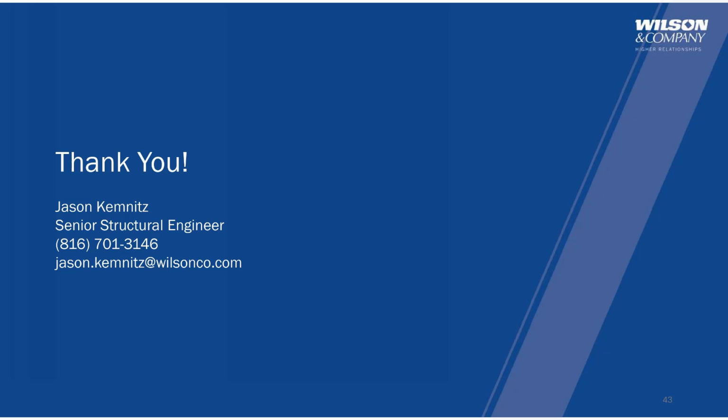Box culvert would take about a solid month. And then if you go next to SDCL, you're looking at maybe 2 months. The traditional, you're looking at maybe 3 months, minimum, right? So I think it's the cost savings on the ground for everybody all around, really. And then as far as designing it, it is pretty simple. So design-wise, it's advantageous to tackle it. It's not more time-consuming than a traditional structure, I would say.